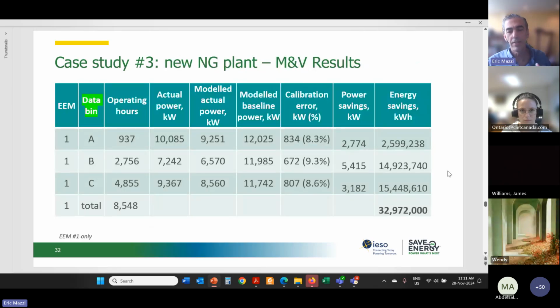And if you're familiar with doing this, the really simple example is, let's say I convert the lighting system in the office I'm in, and I put in new efficient luminaires and I put in lighting controls. Well, if the luminaires are 50% more efficient, or half the power, and the operating time is cut in half, the total power consumption savings is not going to be 50% plus 50%, right? It's not going to be 100%. I'm going to model my luminaire savings first, and then save that as my new baseline, and then see how much I save with the controls, or do it the other way around. It's the same logic with these.